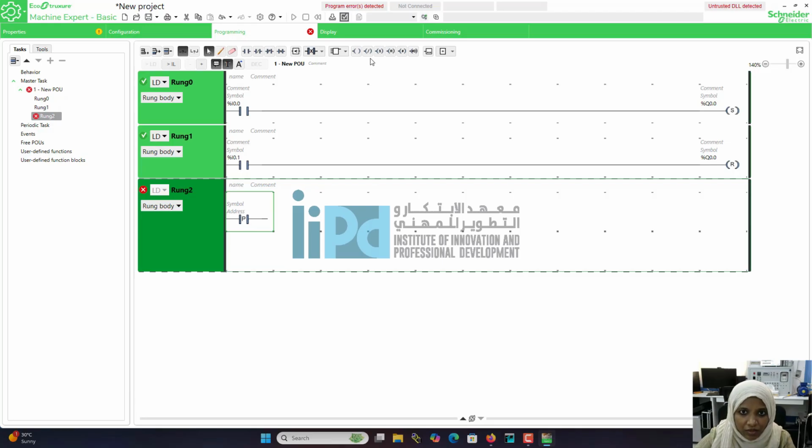Okay. Now if I give a normal output, what happens? When the pulse is generated, the output will come and go. You cannot see it with your bare eyes. So if you want to see that, you have to connect a set switch in order to view your output. So I'll connect a switch. The address means the input into which that change is happening. For example, I have already defined up to I0.1, so I'll go for I0.2. The output will be Q0.1.